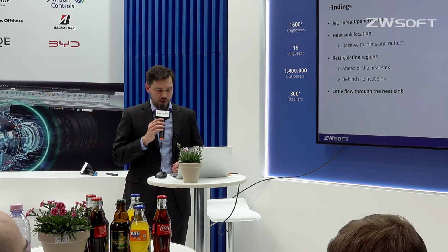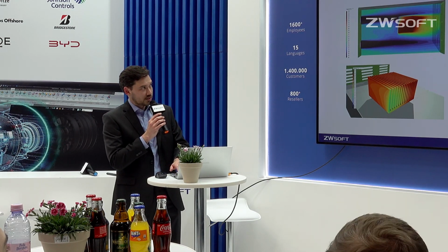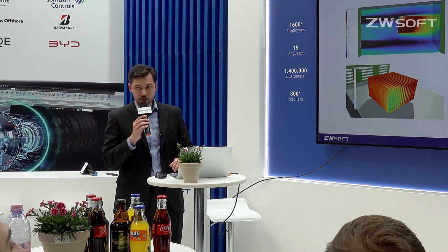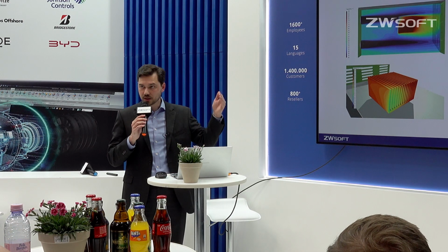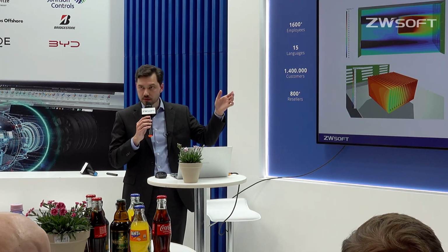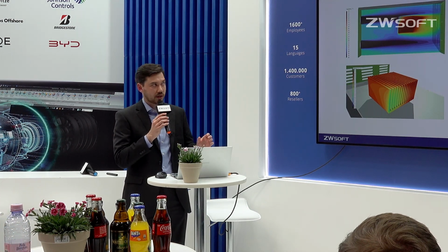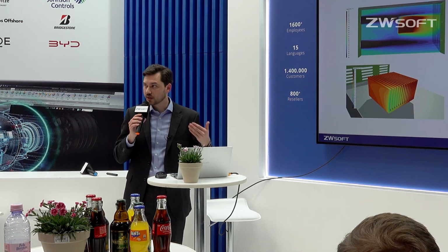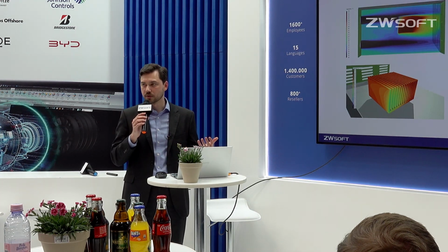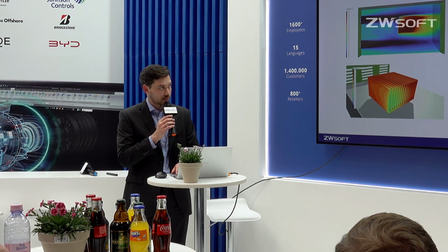And lastly, maybe I'll head back to this picture. We can see that the flow behind the heatsink is also not leaving the domain particularly cleanly. It's got slotted exits, but they also have areas of solid wall between them. And some of the hot flow actually just hits the wall and then turns around because it doesn't have a place to go. And some of that recirculates in the simulation domain.